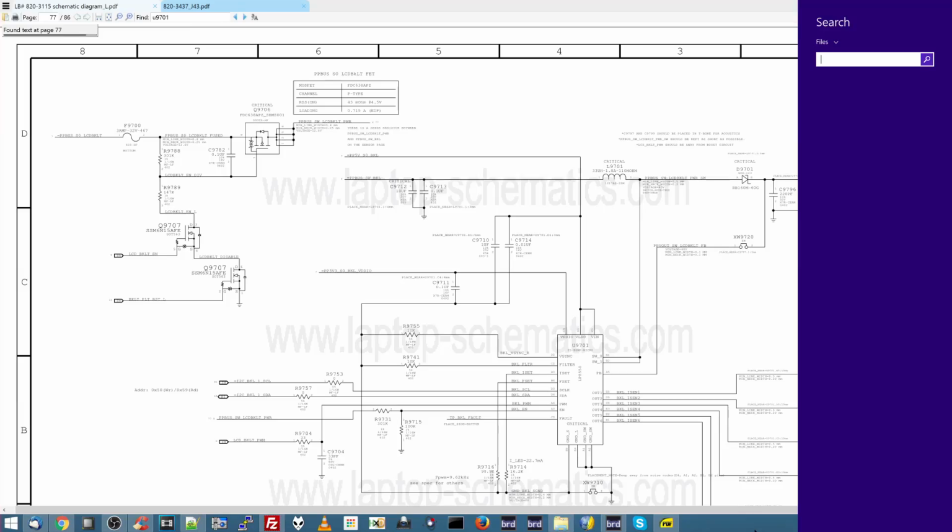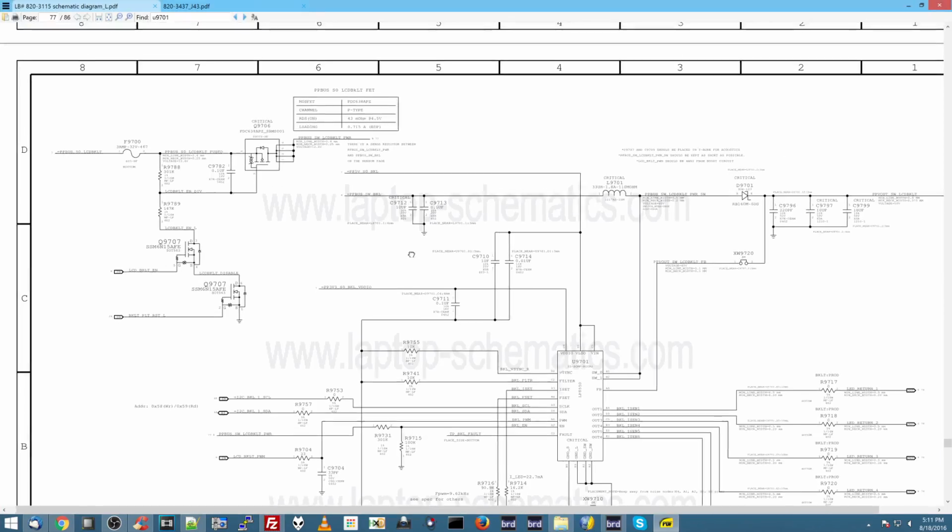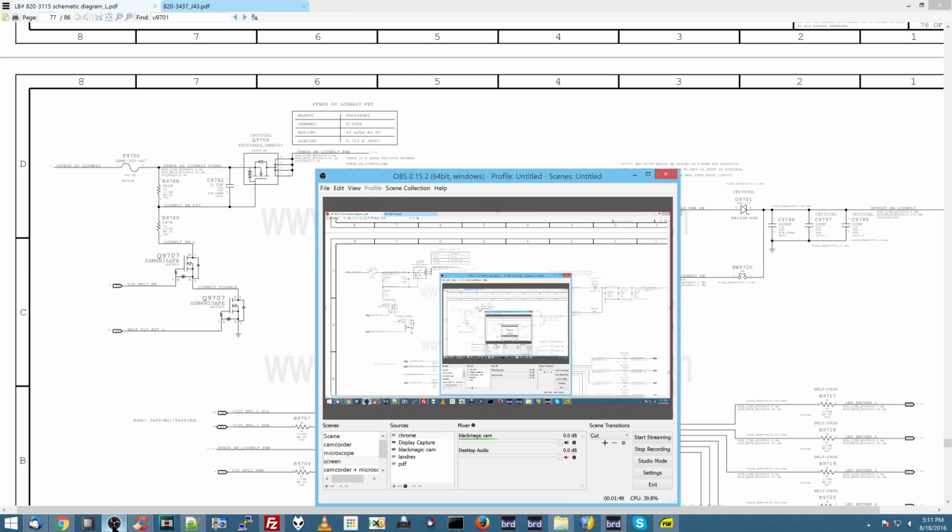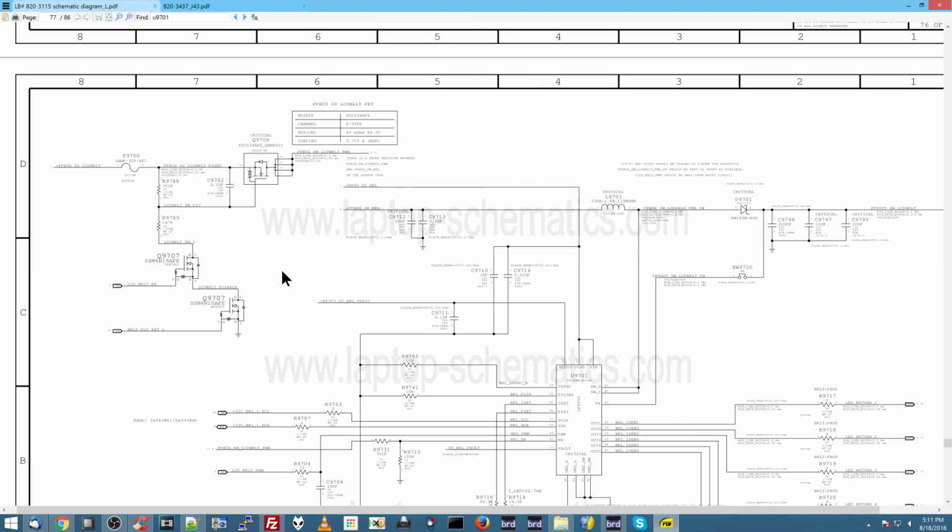Now, let's just take a look over here on the screen and try to get an idea of what's going on. So if I were to go over here and just look for where backlight output is, you're going to see that this is a DC to DC boost circuit. And the idea behind how the DC to DC boost circuit works, it seems complicated, but it's actually quite simple. So we're going to have our 12 volts come in over here. This is our 12 volts coming in through a backlight fuse.